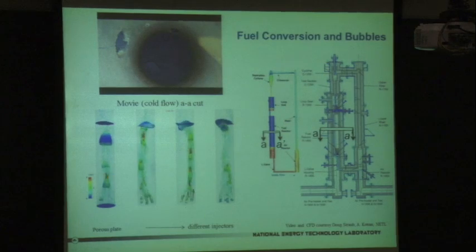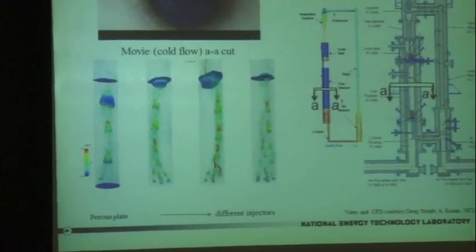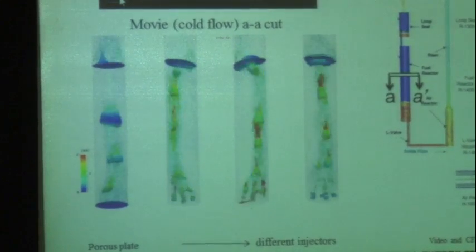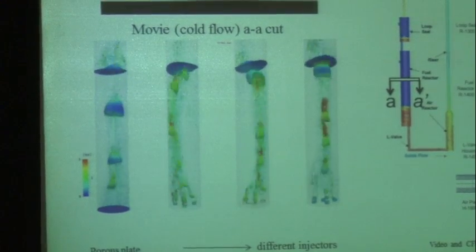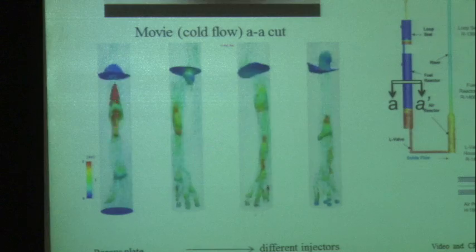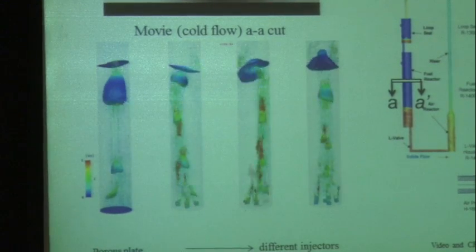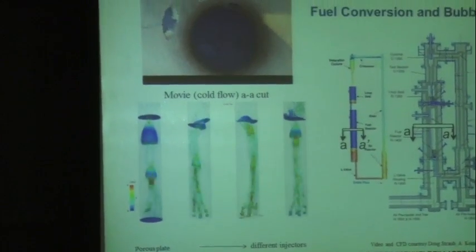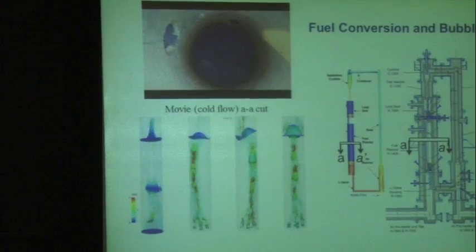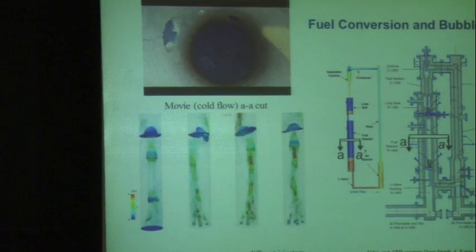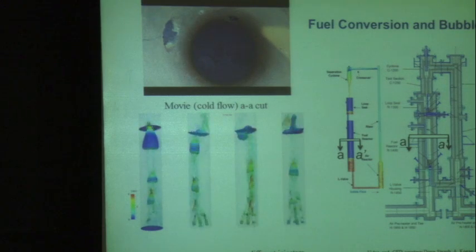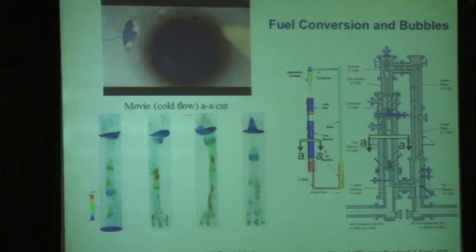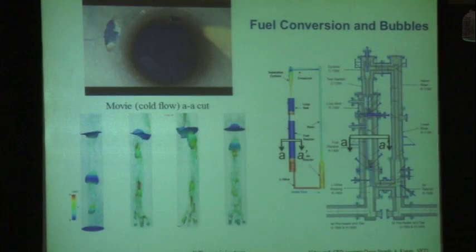So if you look at those bubbles, do you see much difference in the size of the bubble that's coming out of the top? Unfortunately, I didn't. All right? And as they emerge at the top there, they look a lot like what you see in the actual environment where we're running this process. So the point here is, at a given flow rate, the size of those bubbles is more or less determined by the hydrodynamics of the process. You can try making the bubbles smaller, and they'll be smaller right where you're injecting them, but they will coalesce to a natural size. It just has to do with the instability that says at that flow rate there's a requirement to have a bubble moving through that fluid bed.